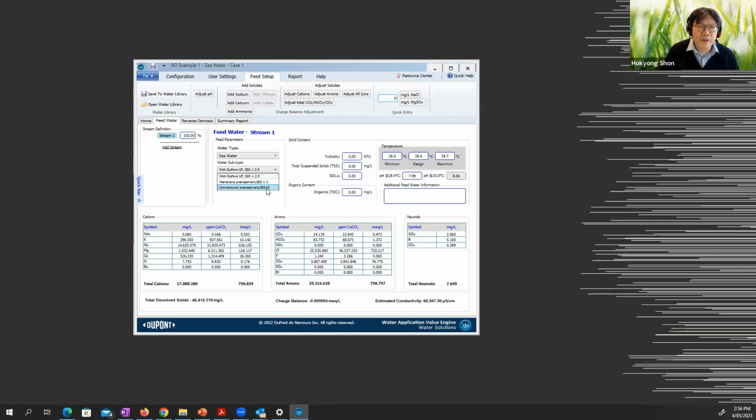So depending on your NTU, this is exactly similar to your ultrafiltration pretreatment, you have a very low NTU. Of course, if you can measure the sample, that's the idea, but low NTU means you have a very good quality of pretreatment.